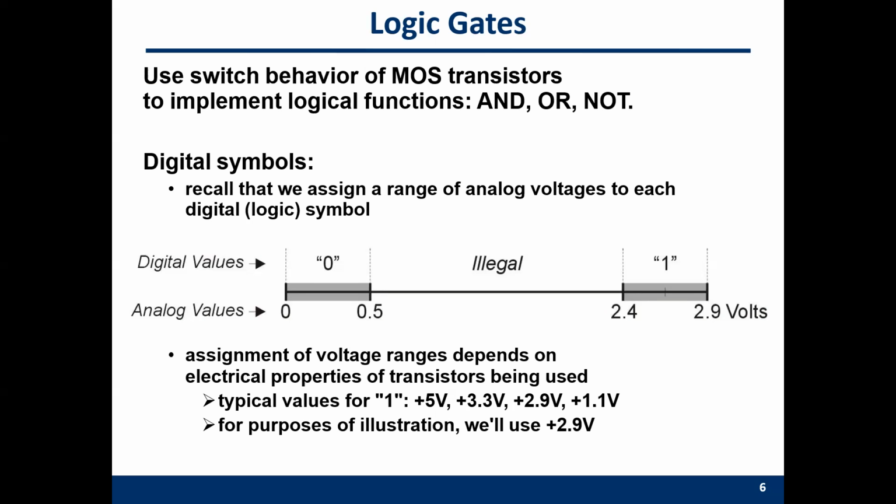For the old physical process technology, like maybe 128 nanometer, the VDD is 2.9. Nowadays, for the 2 nanometer, 4 nanometer, or 8 nanometer, this is 1 volt here.